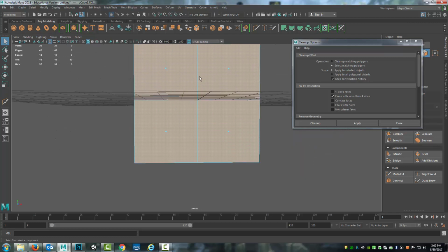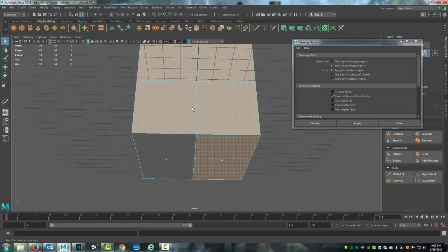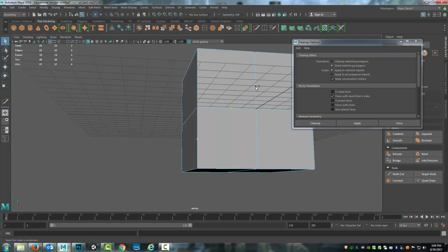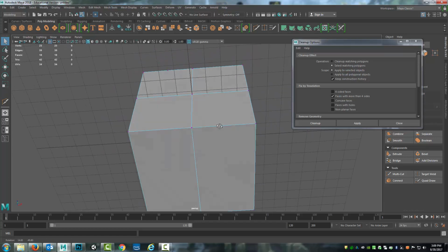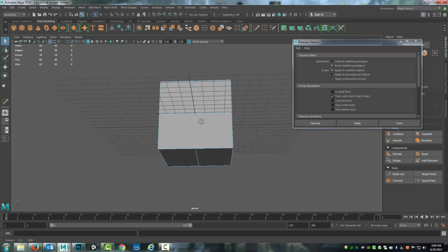Up here where I put in an edge, I deleted the edges, but when you delete an edge, it does not remove the vertices. So if I go to Vertex, you'll see that I still have these 3 vertices that were created. So if I hit backspace, that will actually remove them. The same thing is true right here. Even though it's close, there's actually a second vertex still there. So I can select that, hit backspace to remove it.